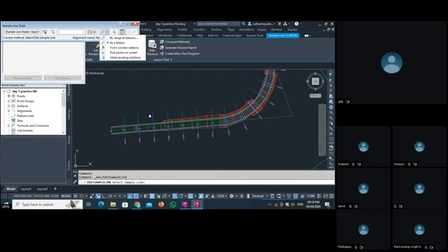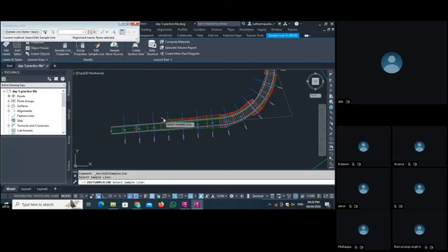With the help of this by range of stations, we create the sample line. Then we go here and create a sample line group. As this is our tick mark, the group is automatically created when we set our by range of stations. If you want to edit this group, delete this group, or select the group from the drawing, you can do it from here also. If you click here, you can see the properties also, but right now we are not providing any data.